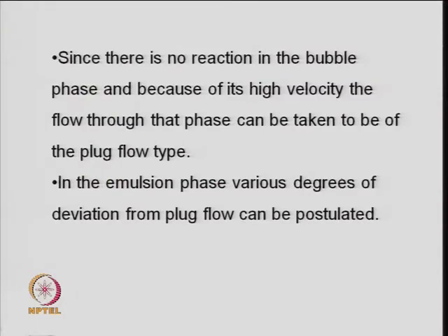We assume that there is negligible reaction in the bubble phase in the two phase model, and because of the high velocity, the flow through that phase can be taken to be plug flow. So, the bubble phase is assumed to be plug flow. But in the emulsion phase, various degrees of deviation from plug flow can be postulated, because the solids are moving up and down. So, there is a kind of back mixing in this, and that cannot be considered as plug flow.